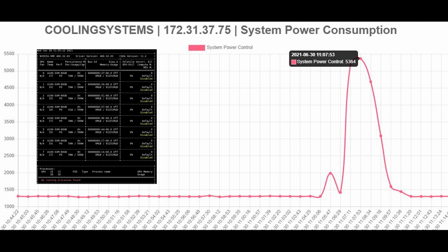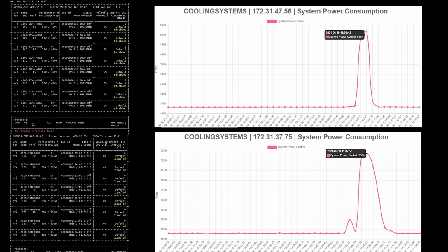And when I say each GPU is using about 100 watts more, you're saying, hey, there are 8 GPUs, 100 watts more, so you should get about 800 watts more power consumption. But we actually only saw about 200 watts more than if we were using the 400 watt GPU solution. So it's 200 watts more, but we got like 20 to 25% more performance.